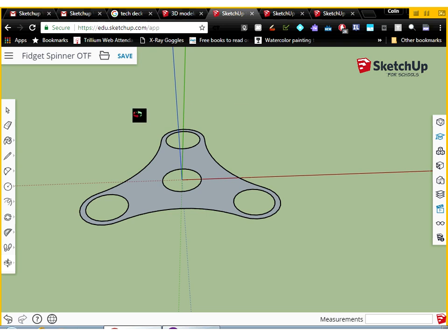And then I'm going to use the most powerful tool in SketchUp, which is something called push-pull. So I can either go to my screen on the left-hand side, and it's accessed about halfway down that tool set. It's this little rectangular prism with an arrow coming out of it, or on your keyboard, it's going to be P for push-pull. And you're going to see that when I hover over top of this shape, it gets this dotted texture to it.